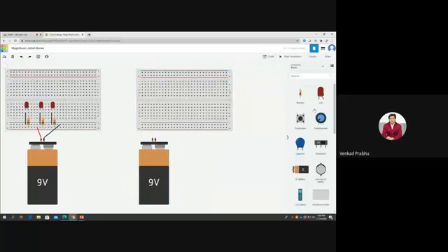Okay, and take an LED now. Now I want to place this LED in the outer part. If I do it like this, is it correct? Can I fix the LED in the outer part like this? I can't connect it, because we can see here that the anode and cathode, which are positive and negative, are in the same negative slot. It should not be like this.